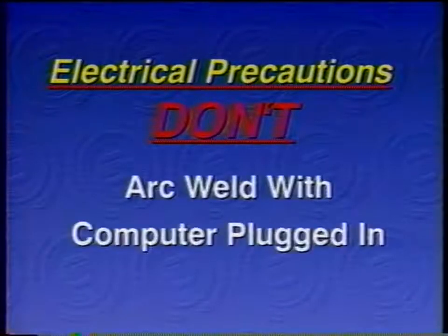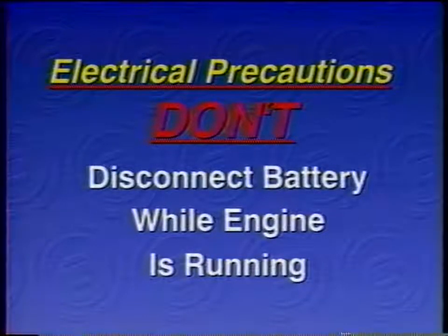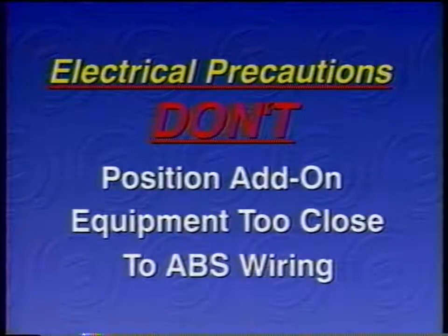Precautions to protect the ABS electrical system include: don't arc weld with the computer plugged in. Don't fast charge the battery with the computer plugged in. Don't disconnect the battery while the engine's running. Don't expose electrical components to high heat. And don't position add-on equipment too close to ABS wiring.